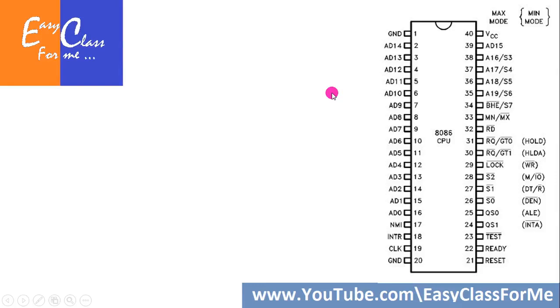So today we will see the function of these pins, and one more thing, that 8086 can be used in 2 different modes. Means when we look at its integrated circuit, it has got 40 pins, and these 40 pins have different meaning in one sense and some different meaning in another sense. So here you can say that there are 2 things written, maximum mode and minimum mode. Minimum mode means when the processor 8086 is only a single processor in the complete circuit that we are using. So we call it as a single mode or minimum mode. And when multiple processors are used in the same circuit, then we call it as maximum mode.